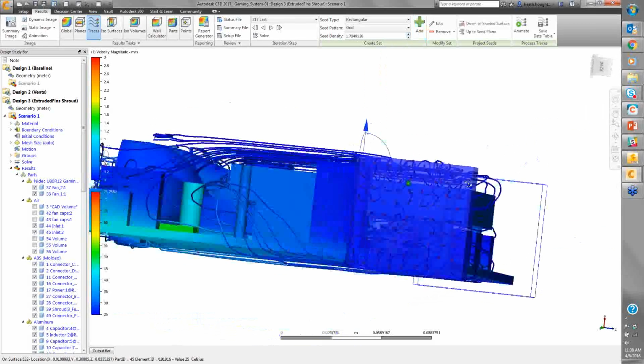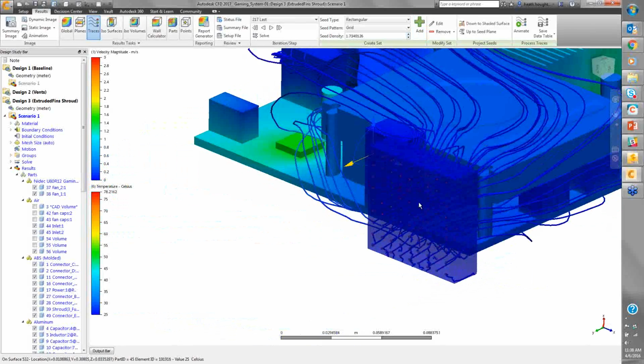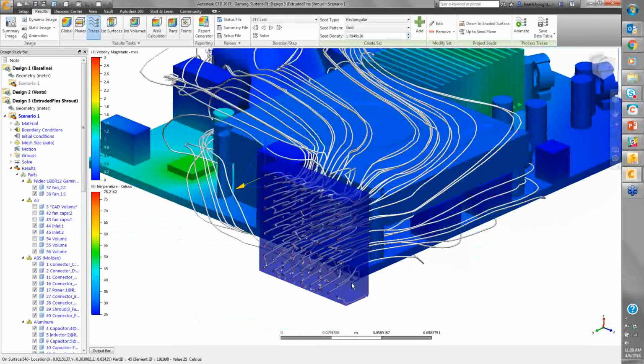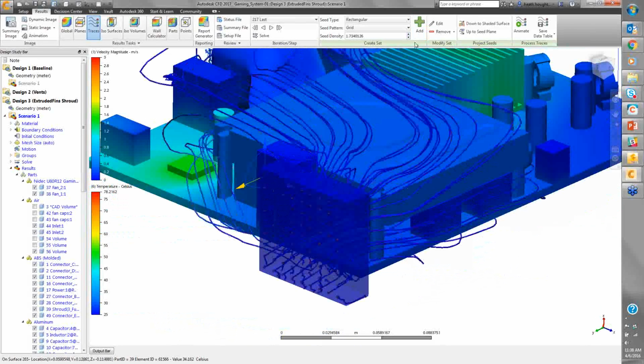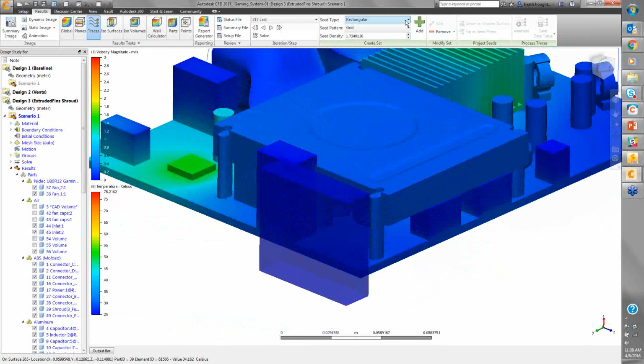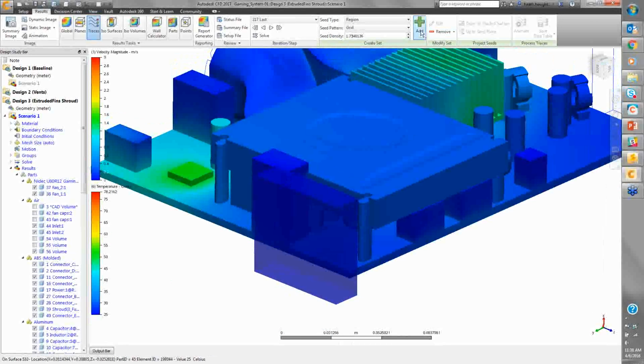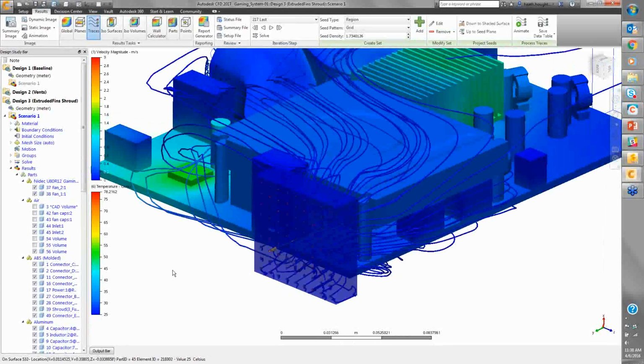But even that, if I want a truly uniform and equally spaced seeding, all from the periphery, there's an even better workflow that we've introduced, and that is the ability to do region. Based off that grid spacing, I click on this inlet. Oops, let me hit add first. I click on this inlet, and automatically, boom, there's your seeding, perfectly uniform at that inlet, or on that face.